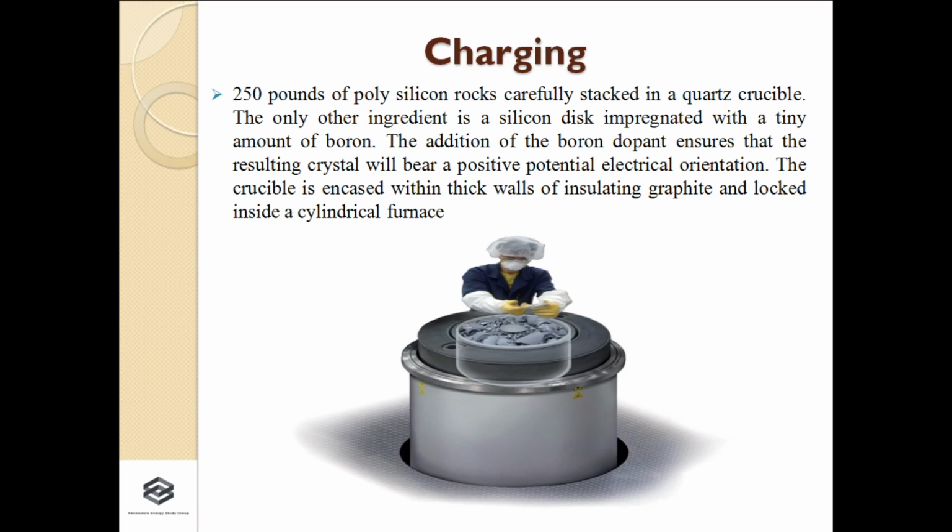So in the first step itself, the material we are preparing is a P type semiconductor material, just by adding a small amount of boron impurity inside this quartz crucible. In this melted silicon we put the boron material, and this boron also gets melted and circulated inside the melted silicon. With this addition of boron, we are preparing the P type semiconductor material, which is the base layer for the silicon cell or the solar cell.